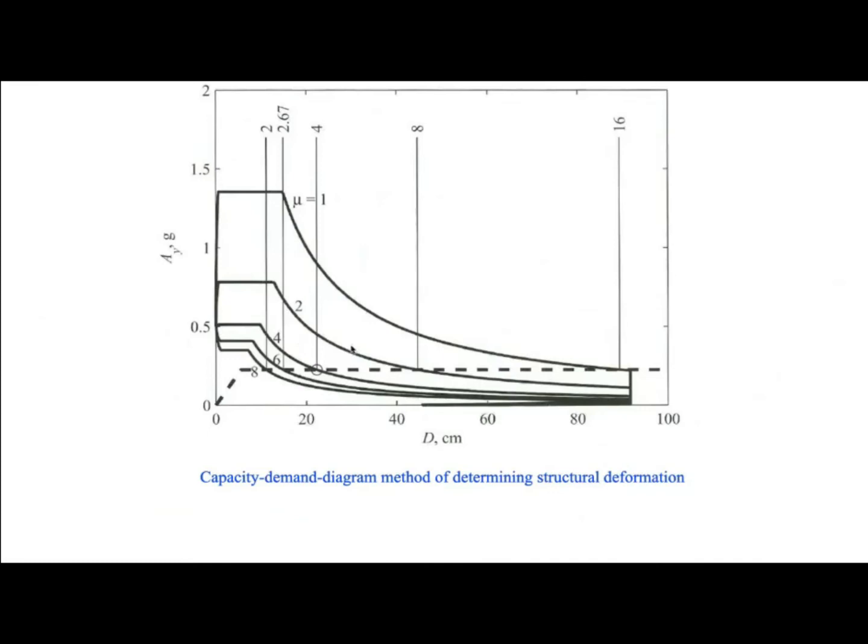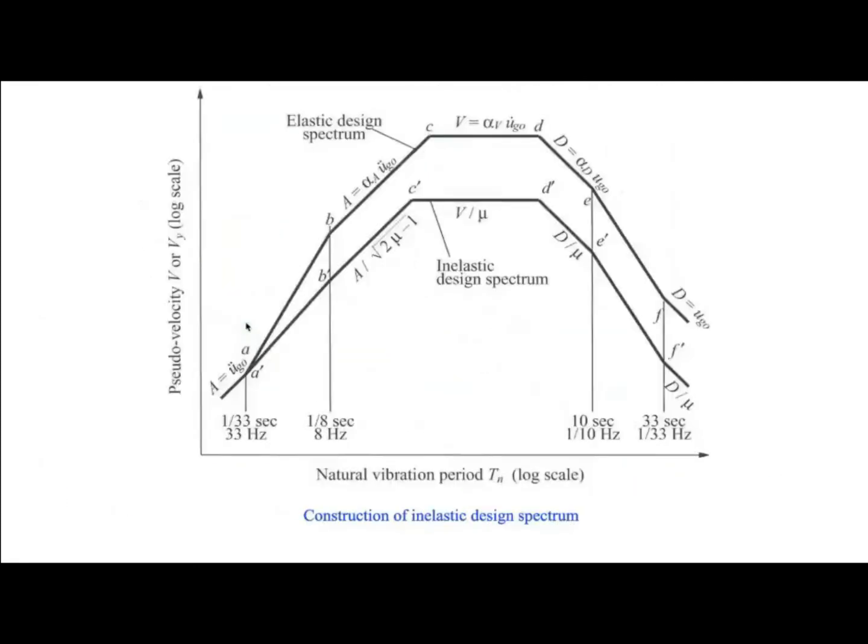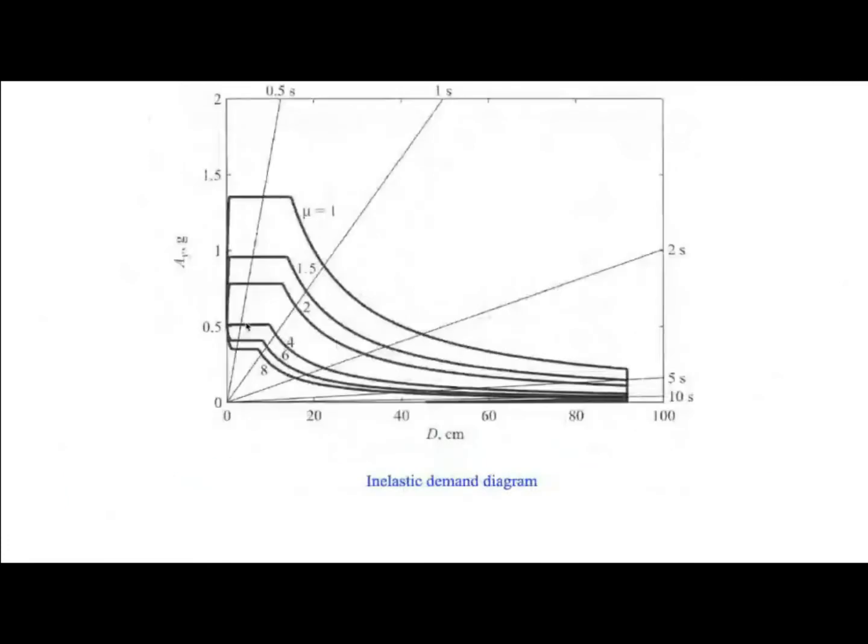For example, in this case, this point gives us the ratio of this displacement to this displacement exactly equal to 4. And the curve is also the one developed for ductility 4. So this is what you want. In this case, the ductility demand on the structural system is 4. Once you know the ductility, then you can obtain the peak deformation demand on the system using this equation.